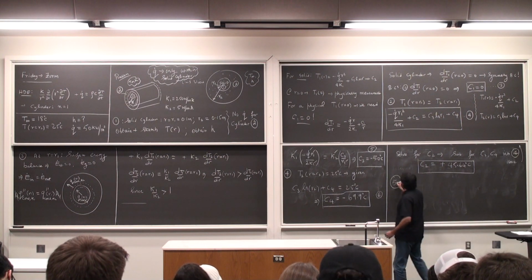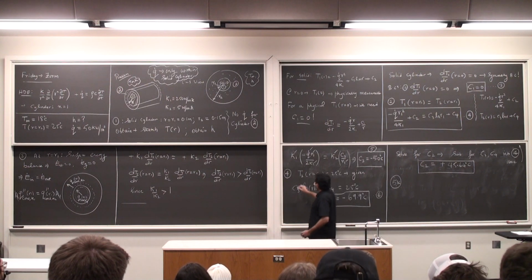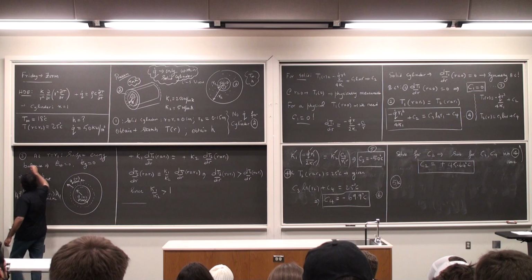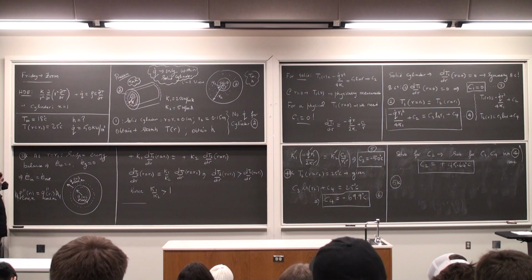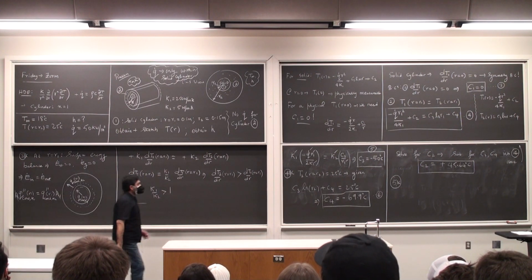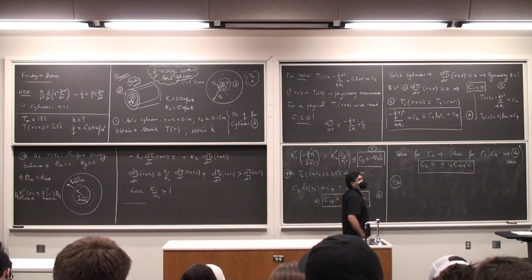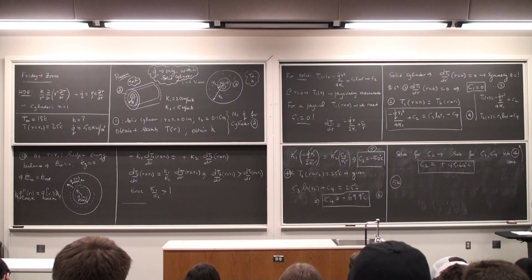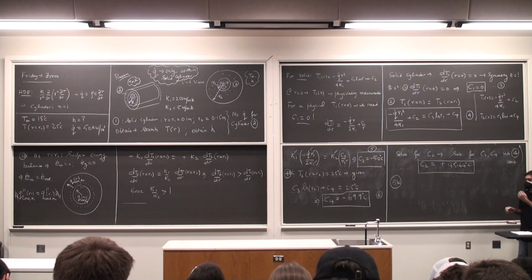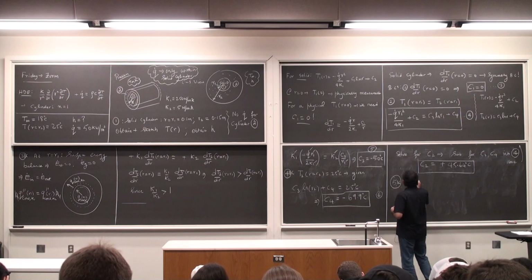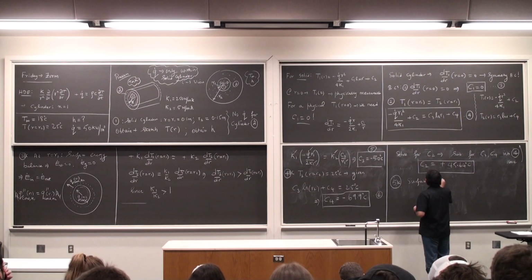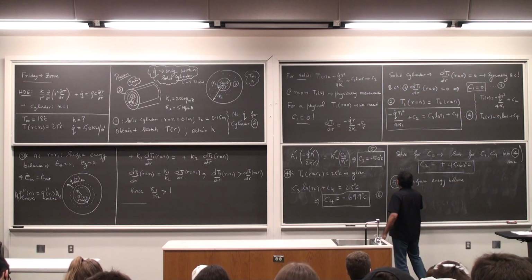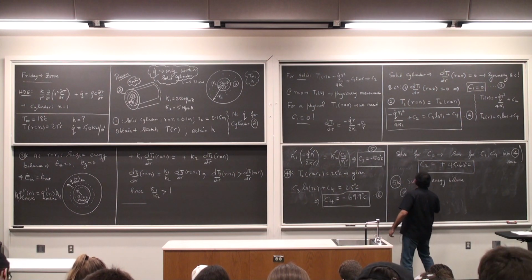This is the boundary condition. I should label it. This is the fourth boundary condition. This is the third boundary condition. Not to confuse with the equation numbers. Okay. In the last boundary condition, I need to calculate the convective heat transfer coefficient so I can perform a surface energy balance at the outermost ring. The surface energy balance at R equal to R2.